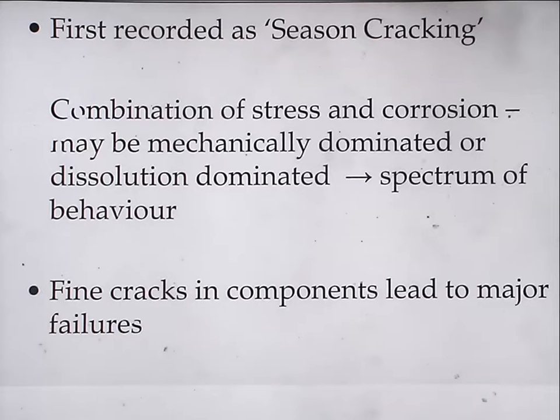Before this concept of a spectrum of mechanisms arose, everybody was fighting with each other, saying, oh, stress corrosion cracking happens this way, no it doesn't, it happens this way, and so there was a lot of argument going on, but in fact it depends on whether you're in a mechanically dominated situation or a chemically dominated situation as to what the mechanism is. The worst thing about it is you've got a component that perhaps superficially looks perfectly good, but is full of fine cracks, and that leads to all sorts of major failures.